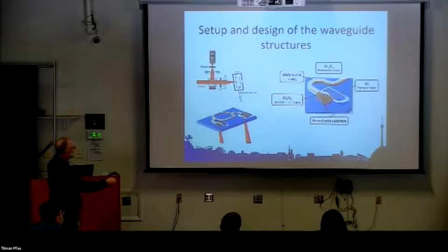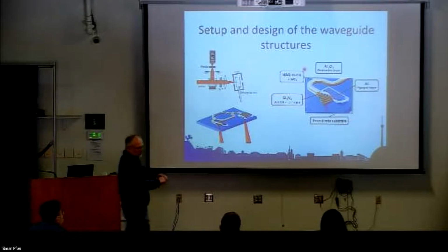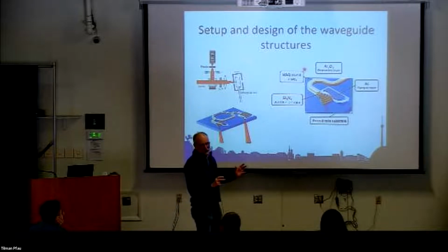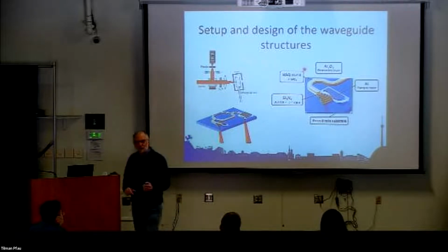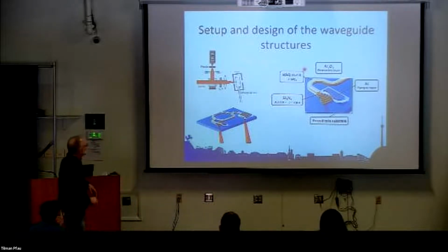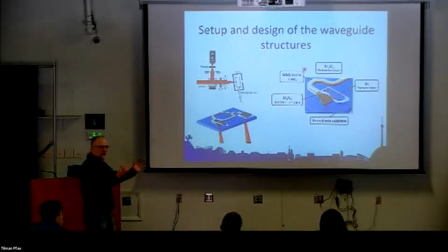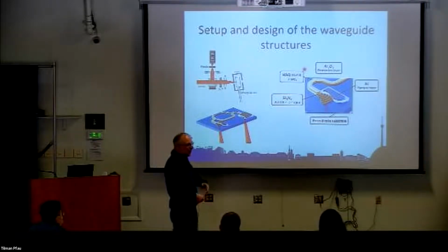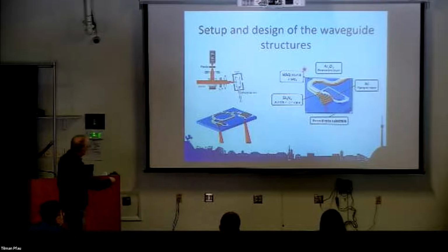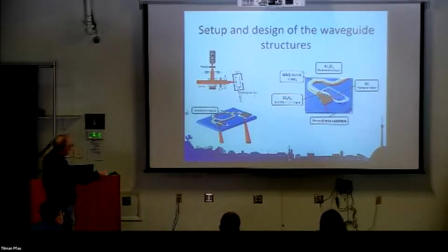And we are using these Bragg couplers here. And we are also using a glass, silicon dioxide cover on these structures such that the guided light is protected from the outside world everywhere except at one interesting position, namely, for example, in that interferometer here.